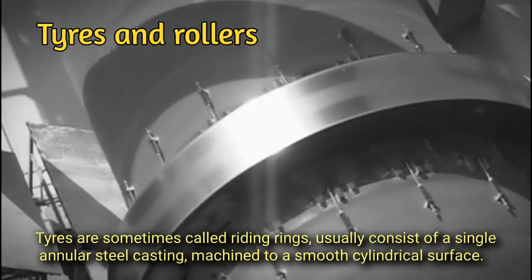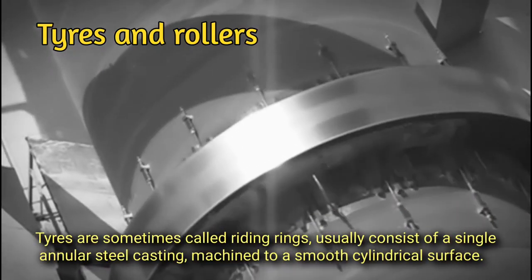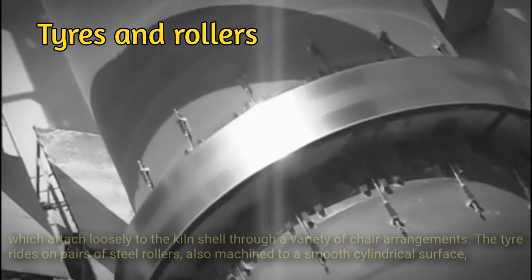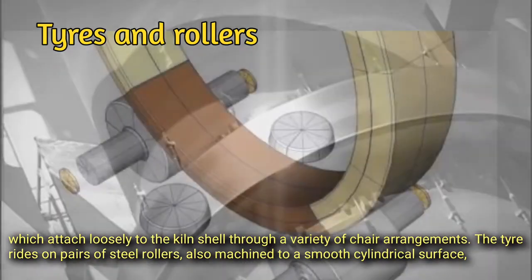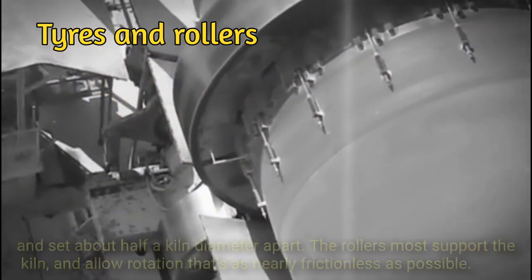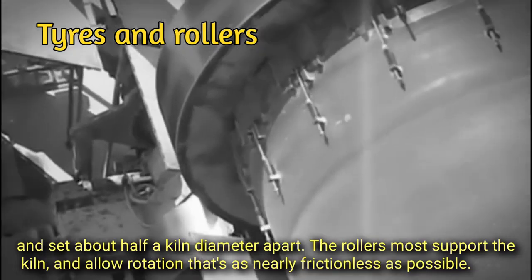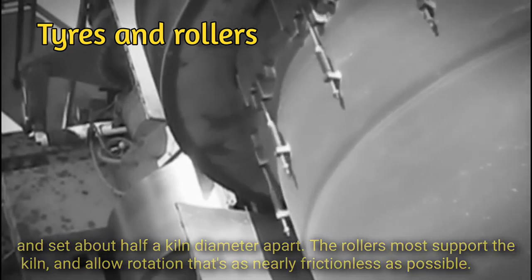Tires and rollers. Tires, sometimes called riding rings, usually consist of a single annular steel casting, machined to a smooth cylindrical surface, which attach loosely to the kiln shell through a variety of chair arrangements. The tire rides on pairs of steel rollers, also machined to a smooth cylindrical surface, and set about half a kiln diameter apart. The rollers must support the kiln, and allow rotation that is as nearly frictionless as possible.